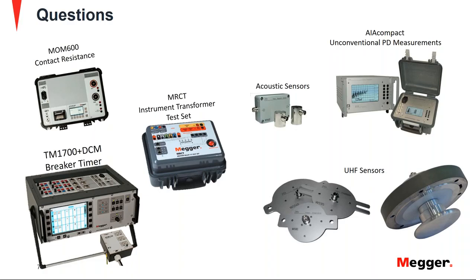So that is a technique that is used to get information about the mechanical condition and the coil condition, the mechanical condition of the breaker and the condition of the coil. In this test, typically in any type of breaker that you run it, you are mainly measuring just the coil current and the voltage that is applied to that coil. In combination with these tests, you can also use some CTs to measure the current on the load side of the breaker.